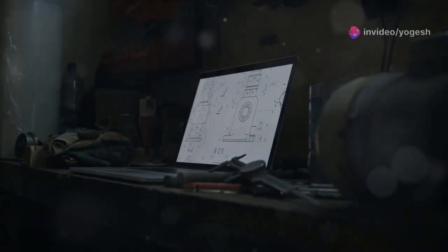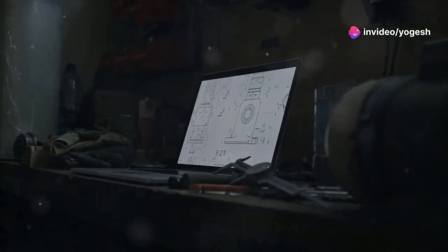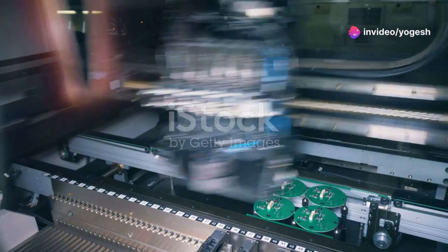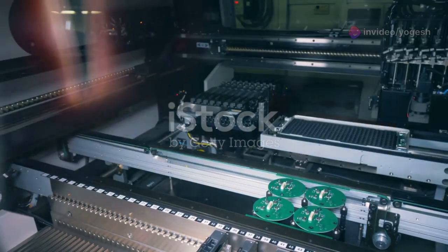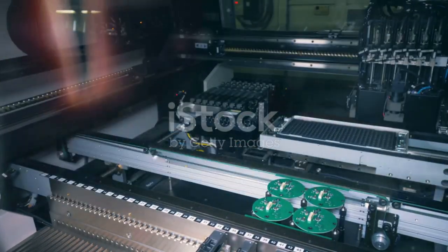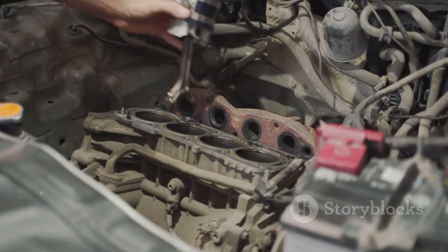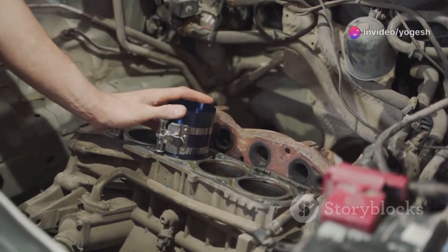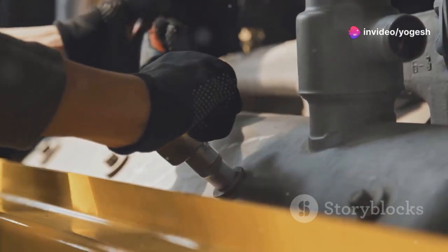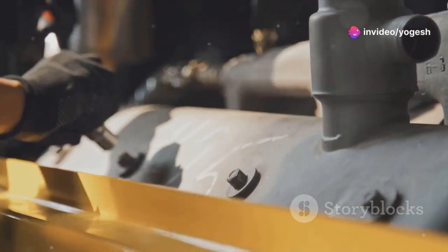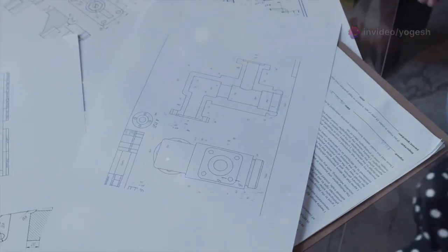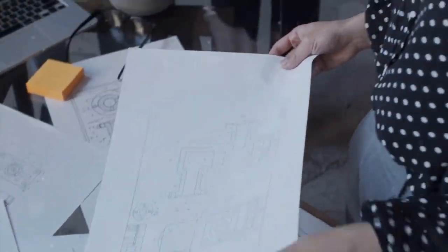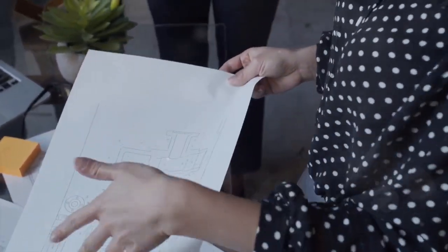For complex assemblies, engineers use assembly stage tables to break the process into clear steps. Each stage lists the operation, the parts involved, and references balloon numbers. For example, Stage 1. Press bearings into the engine block. Stage 2. Apply lube and install crankshaft. This method combines visual and textual instructions, leaving little room for error.